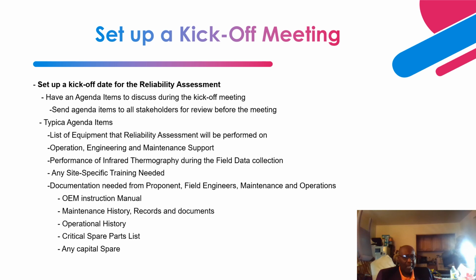As part of the reliability assessment, because it is performed when the equipment is energized, in operation, it is at this point that you perform the infrared thermography, and you need a certified thermography person to perform that to identify hotspots. And you'll be amazed.